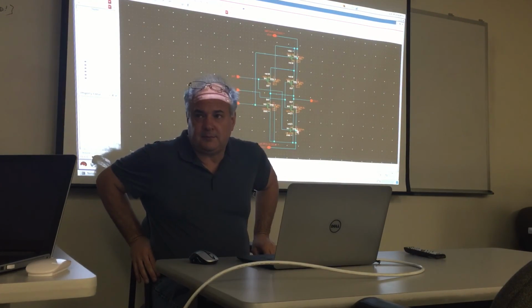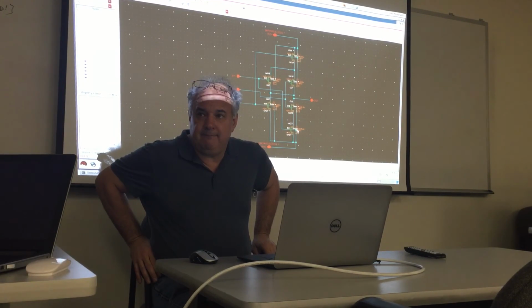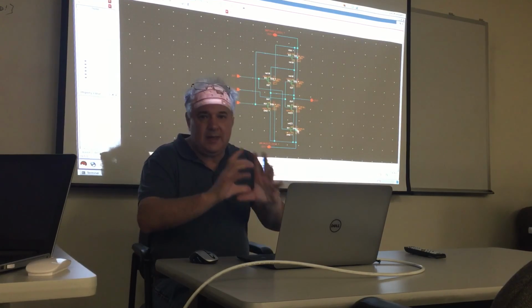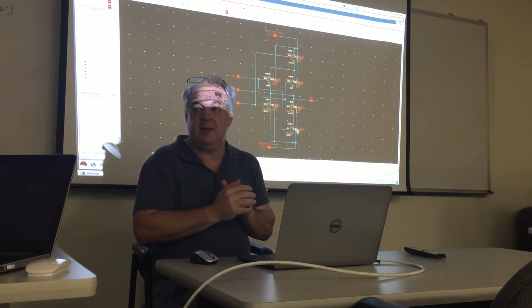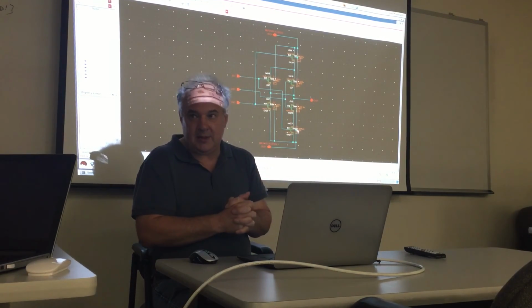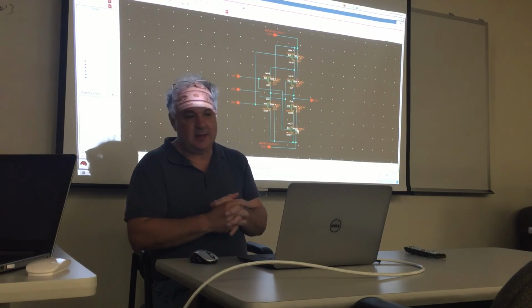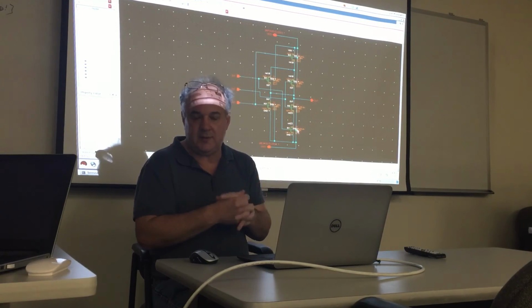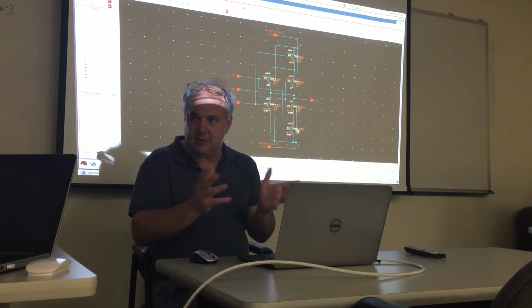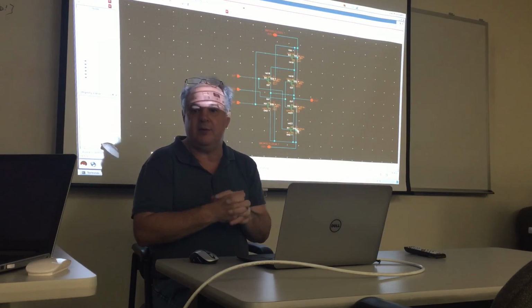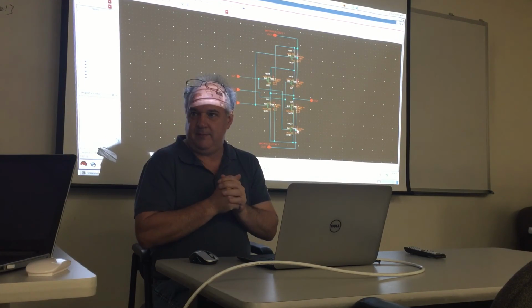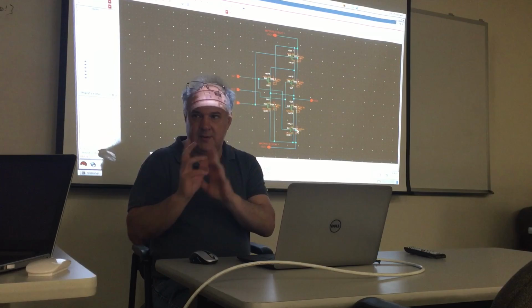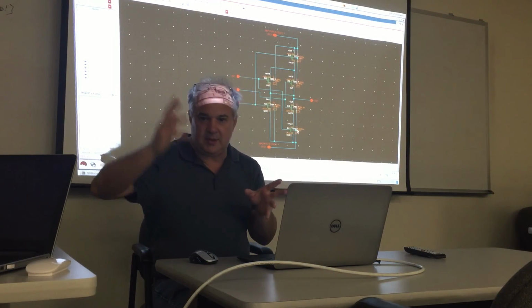So for 4x AO, is it better to make the AOI 2x and then the inverter 4x? Yeah, I would create one set of guts, and I would use them on all 3 designs and use 3 different size inverters. You can do everything internally as 1x, right? That is valid, and it's just gonna be a little slower. I would probably make it 2x because you're actually going through an inverter to speed it up a little bit. Okay. So we can make 2x and then use it across all. Yeah, you use the 2x in the 1x, 2x, and 4x designs. You just change the inverter size.